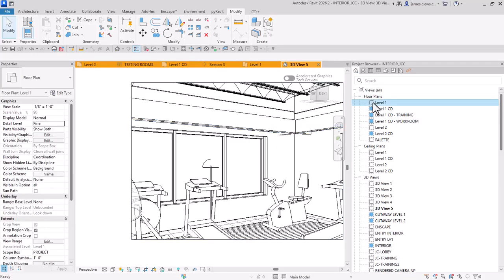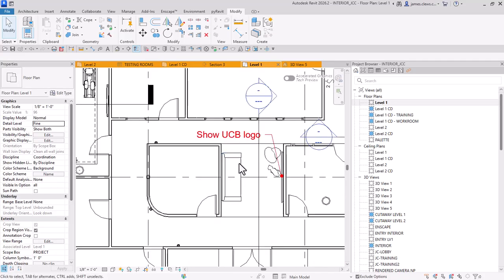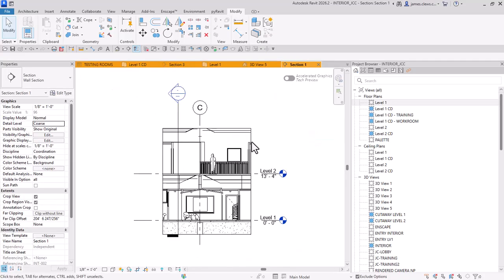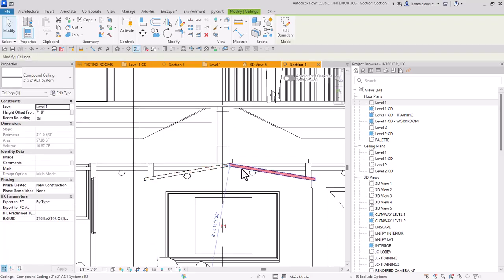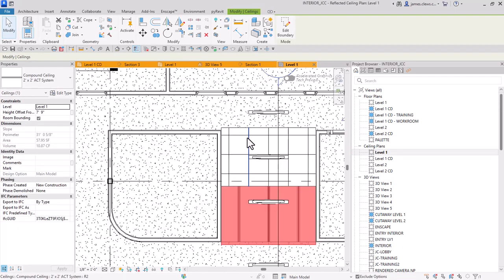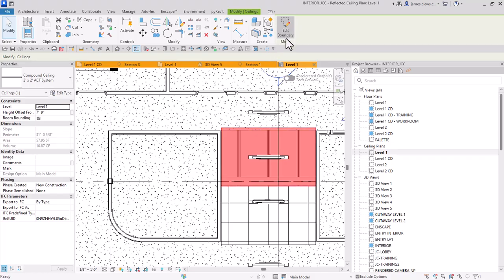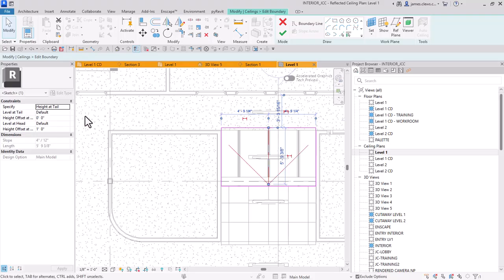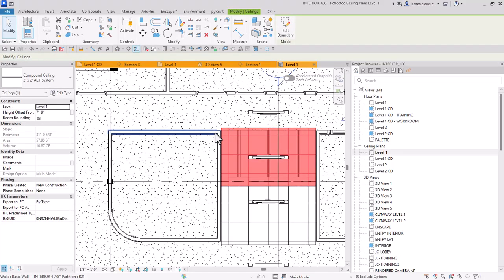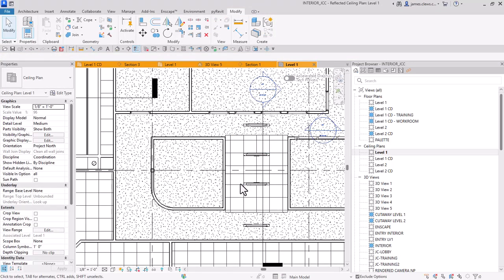There was a sloped ceiling that we did, so that was here. So if I jump in there, that would be this, and mirrored like this. So in plan view, I'm going to go to ceiling plans, level 1. It was inside here that you had a slope, so you had a ceiling, but you used a slope arrow to give a bottom of ceiling and top of ceiling height. So that was 1 foot higher. And then I mirrored it to get the second.